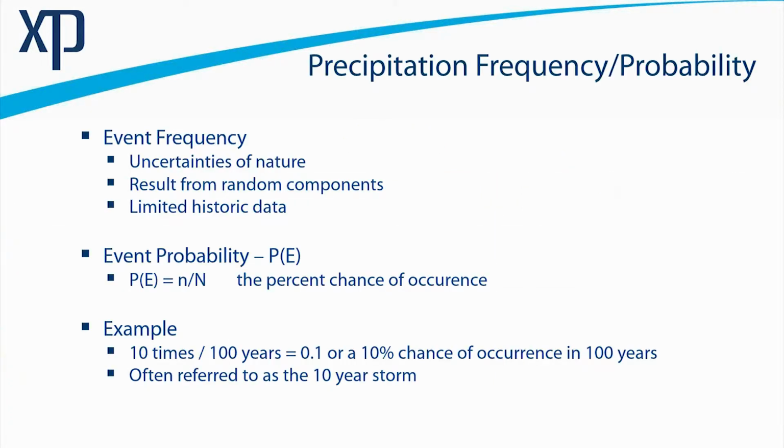And so obviously in the absence of design information, which fortunately Malaysia actually does have a pretty good data set of, you could look at some statistics to back derive your design events, looking at the probabilities of events occurring over time by doing an assessment of your rainfall records. But again, the fact that we have design data in Malaysia makes this not a common task.